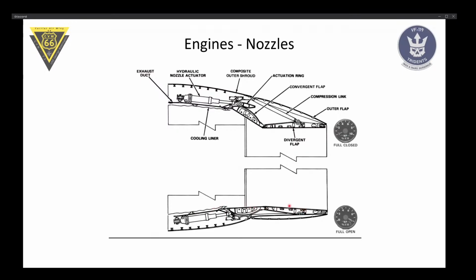And what it does, it is a convergent-divergent nozzle, which means that it has a convergent part and a divergent part. And this is important because at some point, the gases exiting here will be so fast they're going to reach supersonic speed. And if the flow becomes supersonic, it cannot be accelerated using a constrictive geometry anymore. Instead, it needs to have an expanding geometry. So what happens is we're getting high pressure, high velocity flow here, which is accelerated to Mach 1 exactly at that point where the divergent flap begins. And as it enters the divergent part, it accelerates even further to above whatever speed.